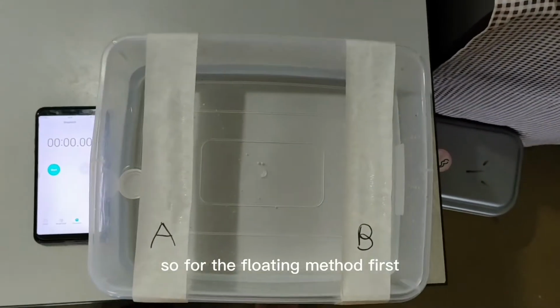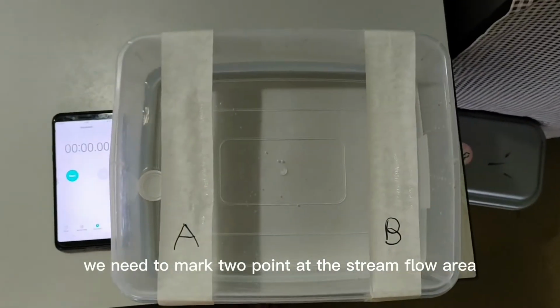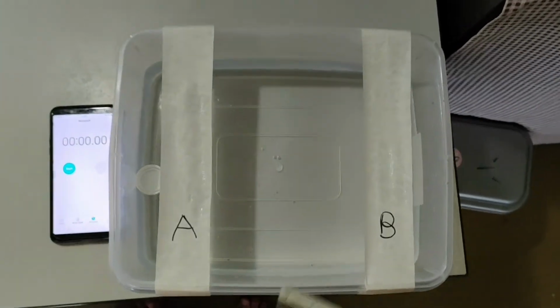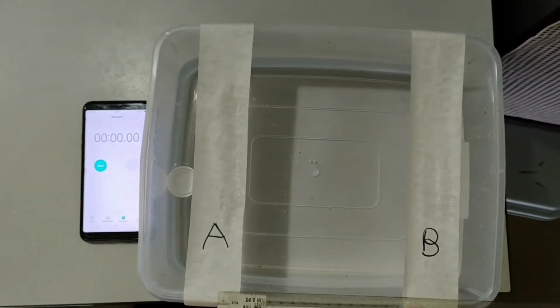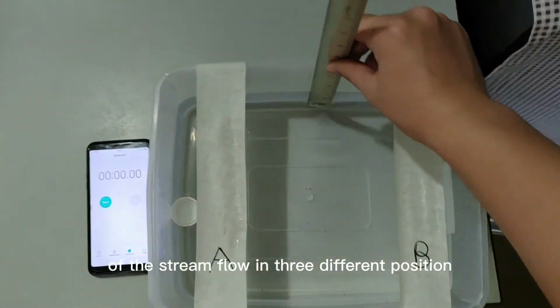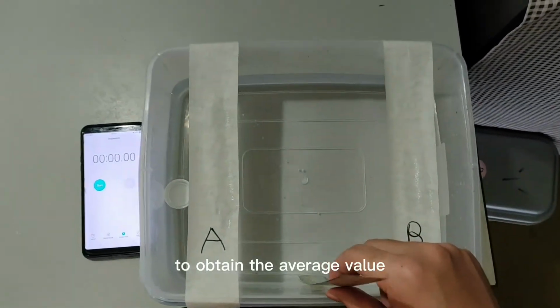For the floating method, first we need to mark 2 points at the stream flow area: point A indicates the starting point, and point B indicates the end point. Next, we measure the distance between point A and point B, and then we measure the depth of the stream flow in 3 different positions to obtain the average value.